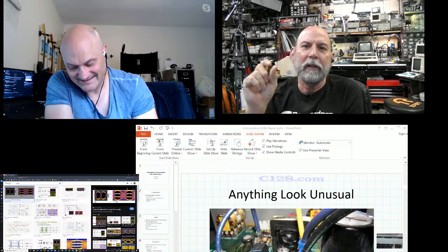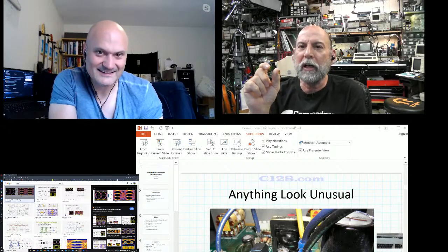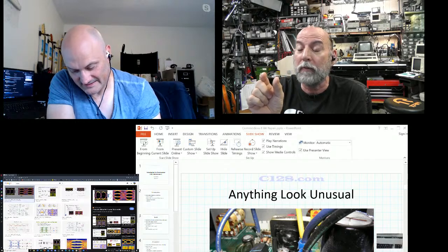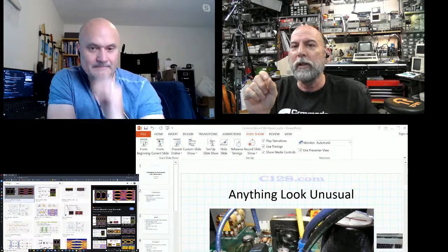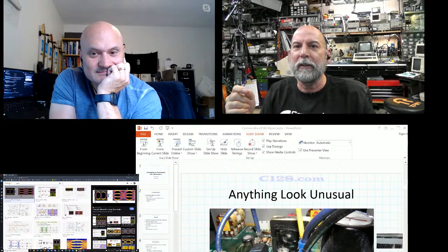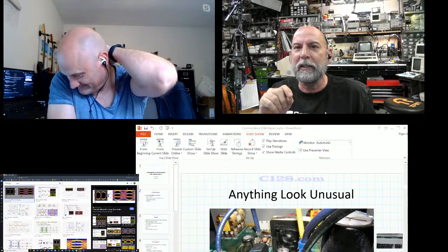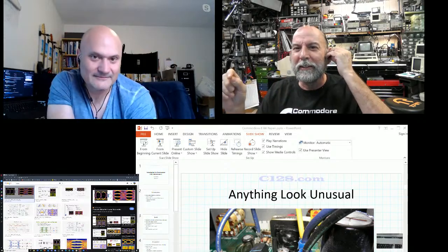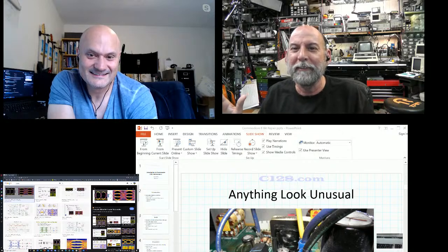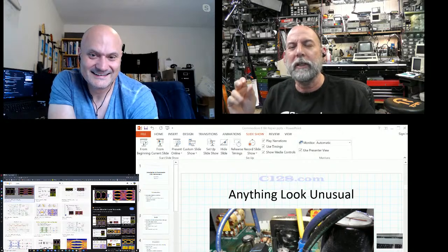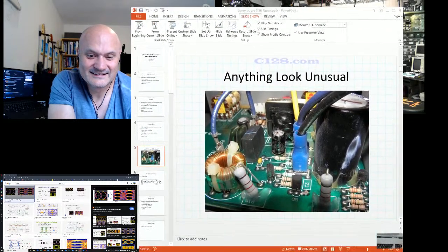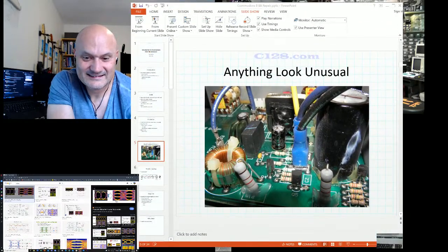And what would happen in the old days is the resistor color codes, the resistors that get so hot, and these typically we used 1/2 watt and 1 watt resistors, that if orange became brown, that's a nonsensical value. Instead of orange, red, you'd see orange, brown, red. You'd go, wait, that's the wrong value. There is no orange, brown, red, right? And that meant that resistor had gotten warm enough that the color had faded on this center band. So look for anything unusual.